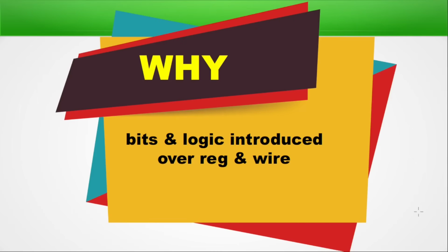One of the important improvements in SystemVerilog is the introduction of bit and logic as new types to replace reg and wire in many situations. These new types are easier to understand, reduce mistakes in code, and help both simulators and synthesizers work better. In this presentation, we are going to explore why bit and logic were introduced, how they work compared to older types, and how they make digital design simpler, more powerful, and more reliable. So without any further delay, let's begin today's episode.